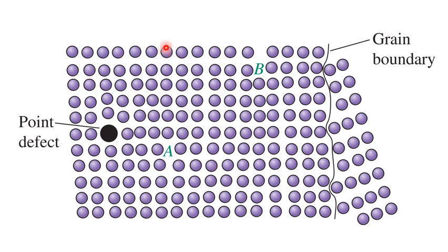Thus, strain hardening is increasing the strength of the material by increasing the number of dislocations inside the material, causing interaction or disruption of the dislocation movement across the material due to the interaction among the dislocations.